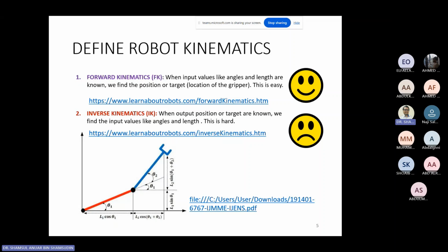Okay, so for those who have taken the class with me before in mechanical system design, like Manish and Arshad, this is where we are different from the previous way of doing things. In the forward kinematics, we tend to use the absolute angle, whereas in the inverse kinematics we use the relative. This one absolute, this one relative.